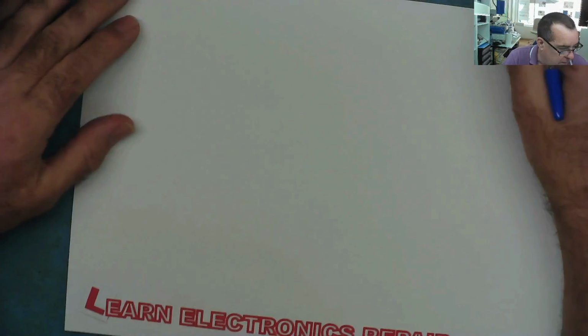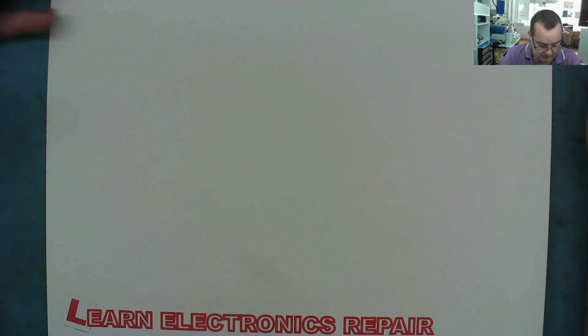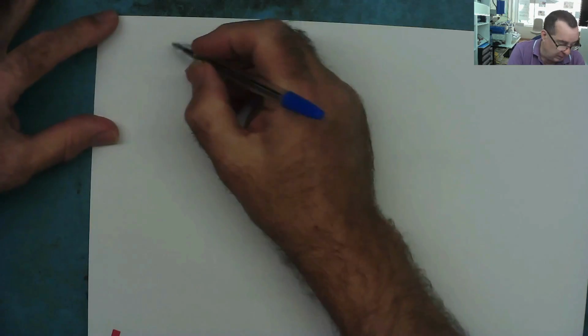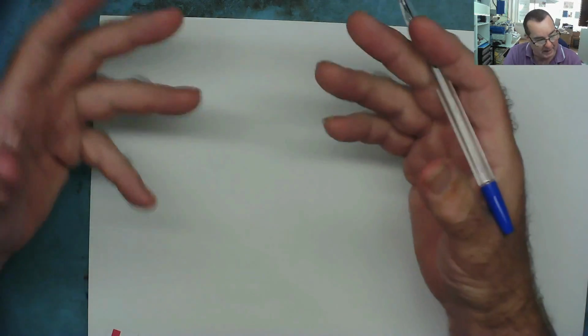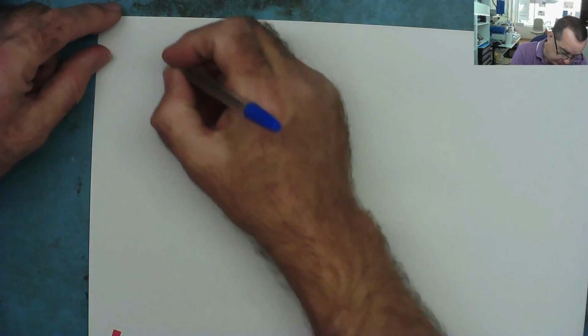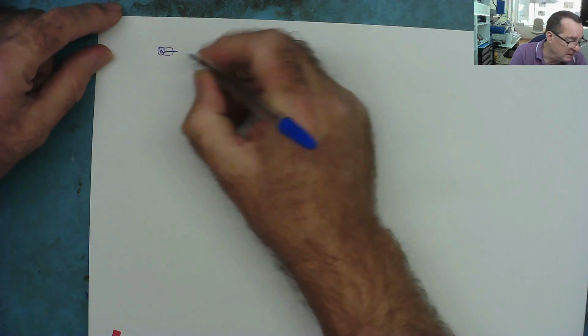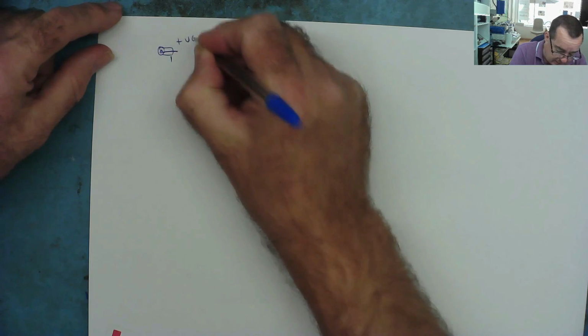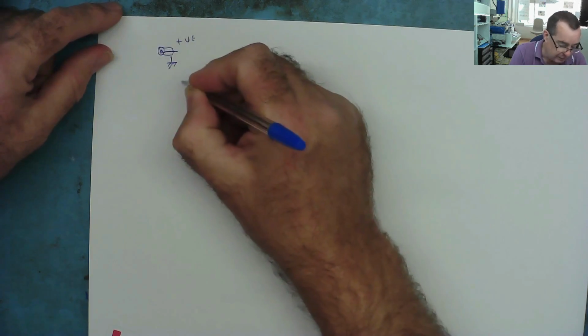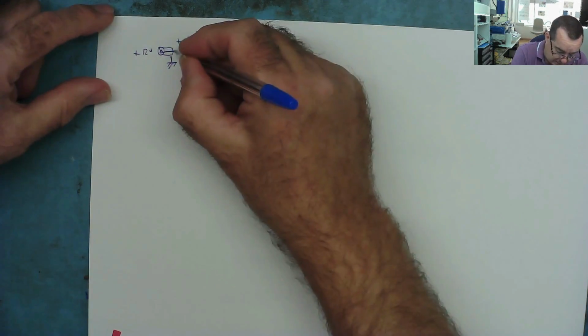Let's just have a talk about where we're likely to find diodes used in circuits. Diodes have many, many uses, but these are a few examples of where you would find diodes in circuits. A very simple example would be a device that's powered from a mains power pack, a wall wart, if you like the American term. On this you will have a jack socket with a center pin, and the center pin is usually positive, and then the negative goes to ground, and this is plus 12 volts or 5 volts or whatever the device requires.